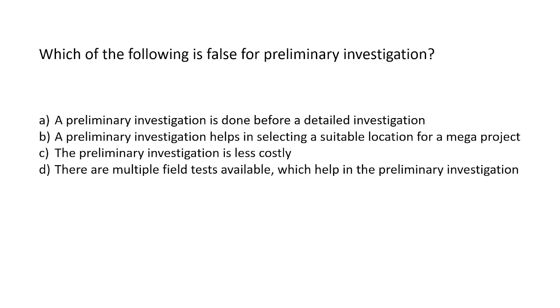Third one: preliminary investigation is less costly. Obviously it will incur some expenses, but compared with the detailed investigation, it is very less costly, very cheap. Next: there are multiple field tests available which help in preliminary investigation. The multiple field tests we go for only after the preliminary investigation, when we want to know the site in detail, right? So the last option is not true for preliminary investigation. The answer for this question will be D. Okay, let's move on to the next question.